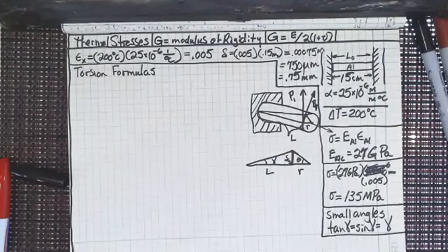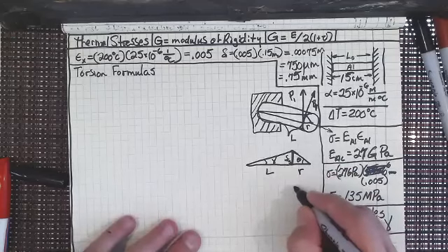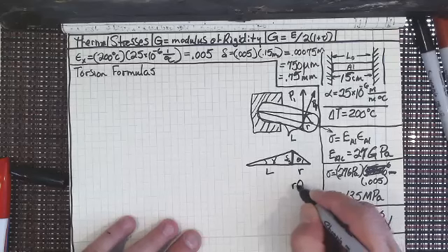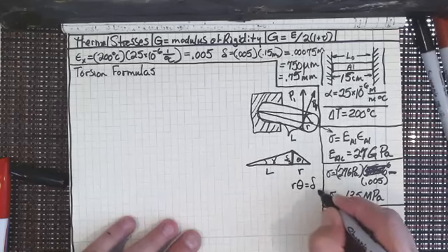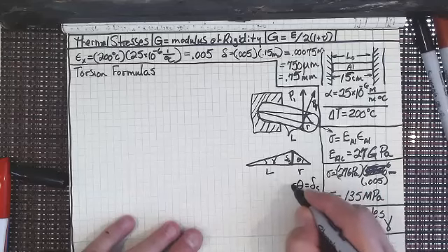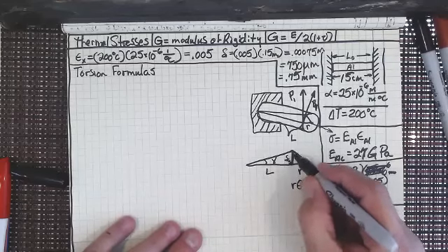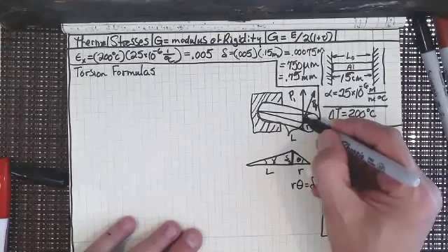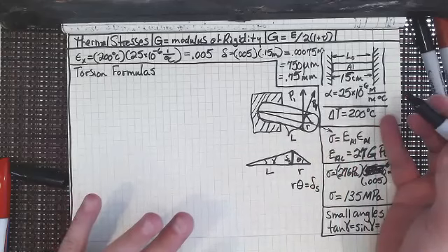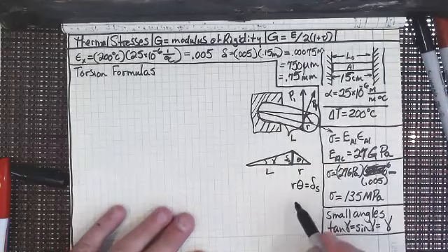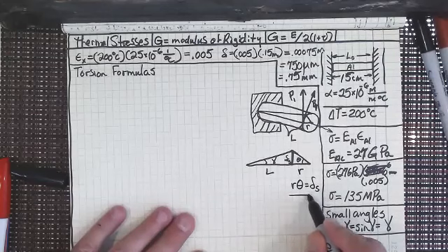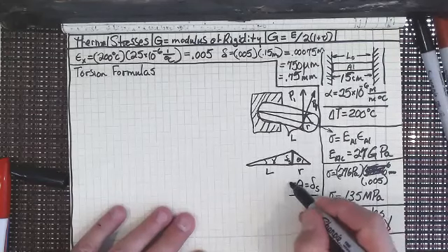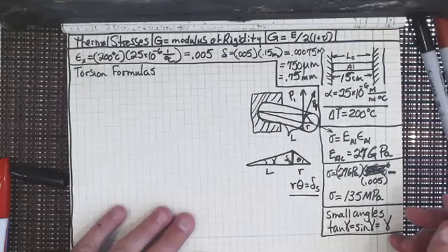So I know that this distance here would be R times theta, equals that deformation. If we were looking at this as an arc, which we've got right here, and we're saying that arc and the segment that connects those two are the same. So we're using this approximation for small angles. So R times theta equals delta sub s.